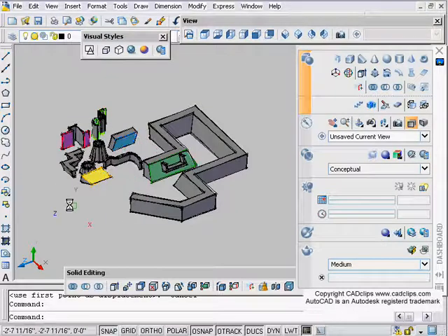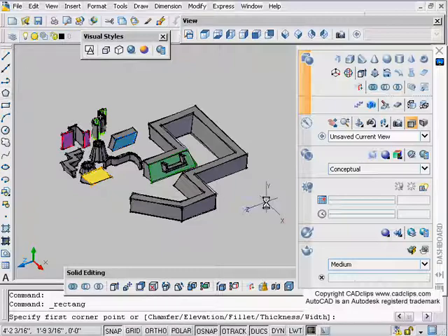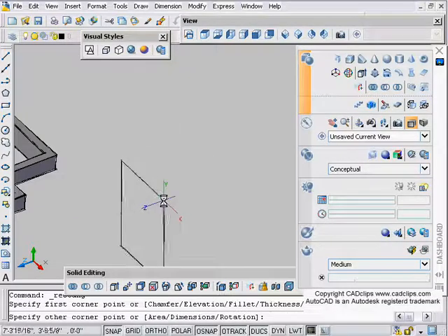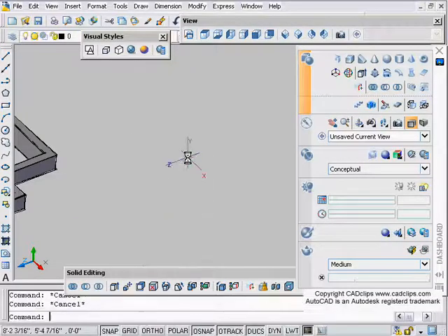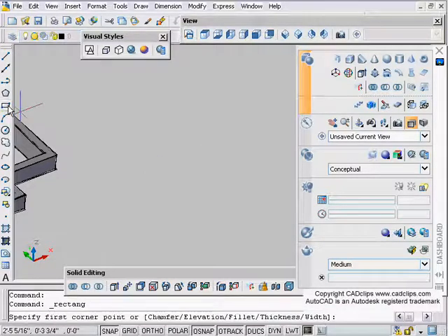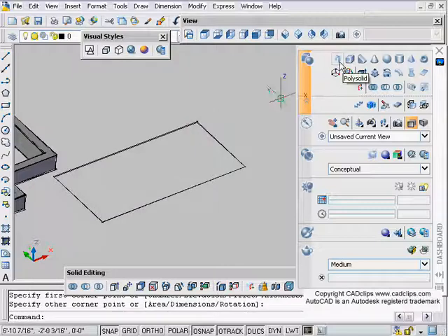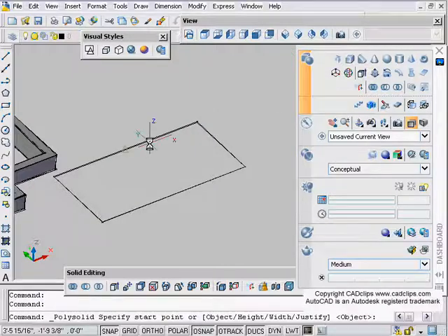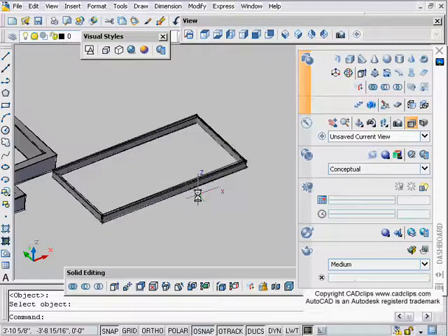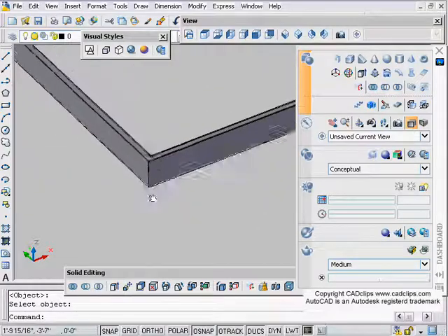Have a look at your command line, convert existing geometry lines. I would go in and maybe try some more of these shapes. Very quickly, it'd be easy to go in and make a rectangle. Oh, let's do UCS world. That's probably my problem. Make a rectangle box, pick on my Polysolid, enter, pick on here, and you're done.